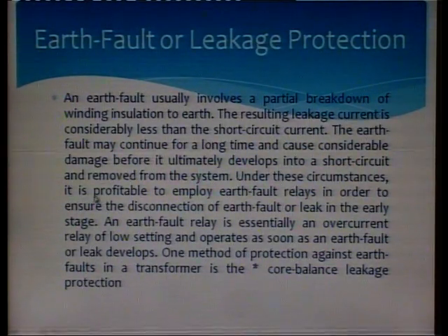So, that's why earth fault protection becomes necessary for the transformer. So, under these circumstances it is profitable to employ earth fault relays in order to ensure the disconnection of earth fault or leak in the early stage.